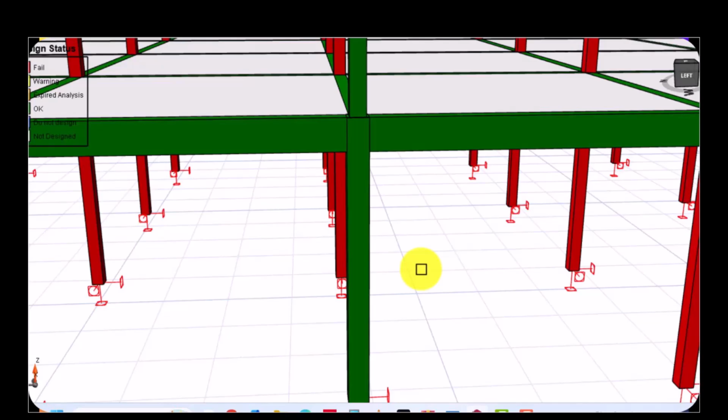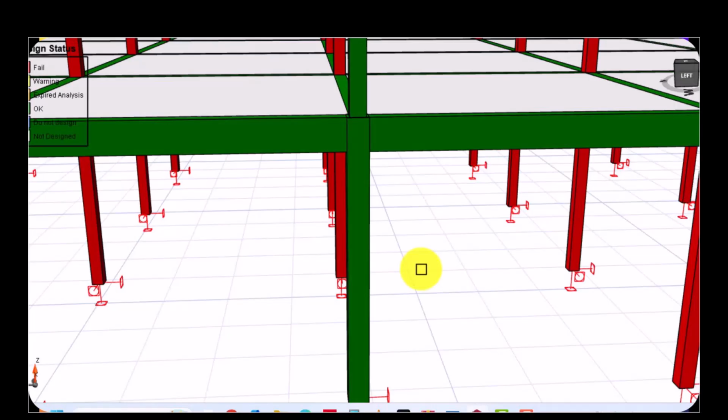The fourth reason that I would like to emphasize is that right from the textbooks, we always assume that columns are under axial loads only, but in real life scenarios that's never the case, because columns also carry bending from the structural members they are supporting. So small columns like 225 by 225 will lose their capacity rapidly under that combination.